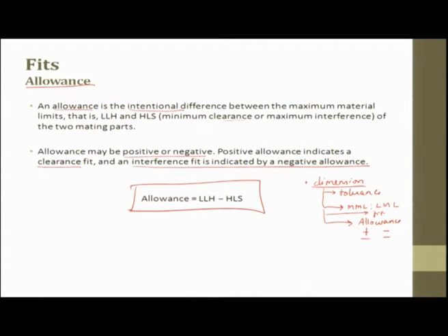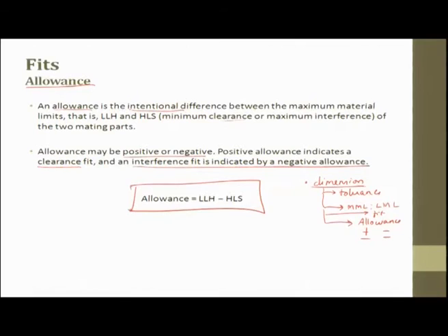First we saw tolerances, which give the maximum and minimum. What is the use of maximum and minimum? We are trying to find out the fit, and once you find the fit, we find out the allowances. Before that, I would like to put a small schematic diagram: clearance, interference and transition.